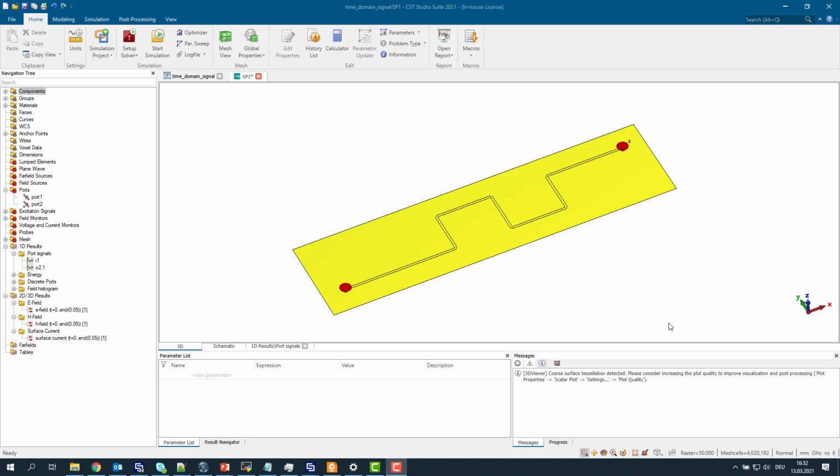Many times the field animations are shown in the frequency domain, because people tend to use a finite element method, which calculates in the frequency domain. So they show a steady state behavior of the pulse on a signal trace and not the real time domain. This is why I chose the time domain solver inside CST Microwave Studio to visualize these fields really in time domain for you.